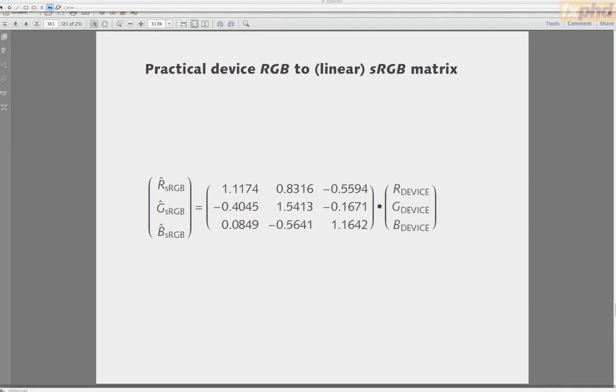So Margaret is asking, is the ColorEdge CG243W, when it's set to wide gamut, displaying SMPTE DCI-P3? And the quick answer is, I don't think so. I think when you set CG243W to wide gamut, that is its description of native gamut. So the native optical properties of the illumination and of the LCD are a little tiny bit wider than P3.